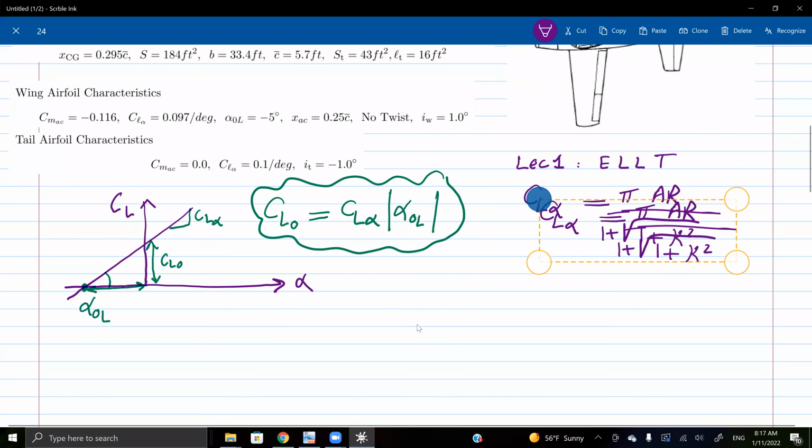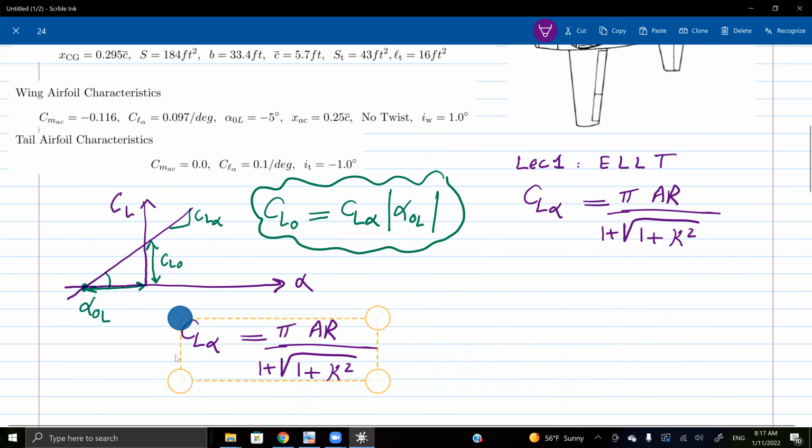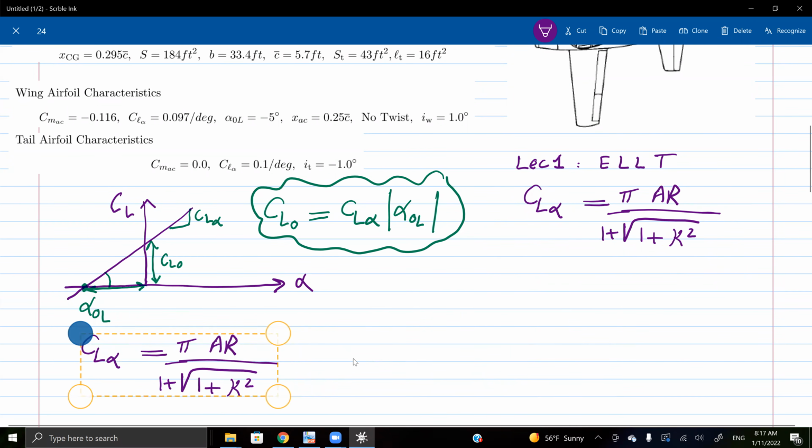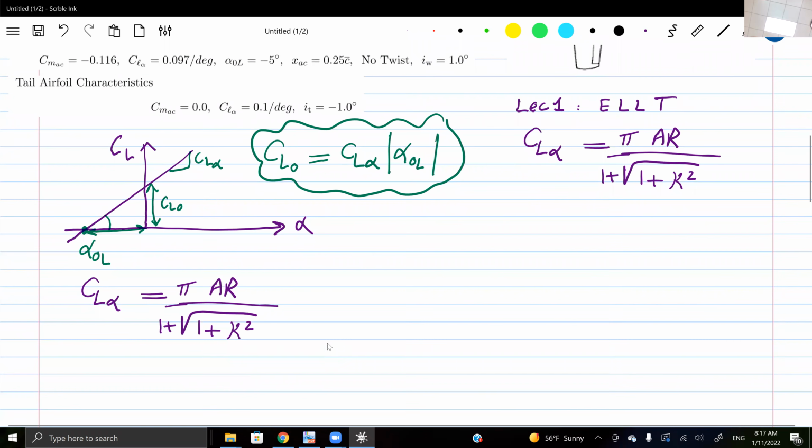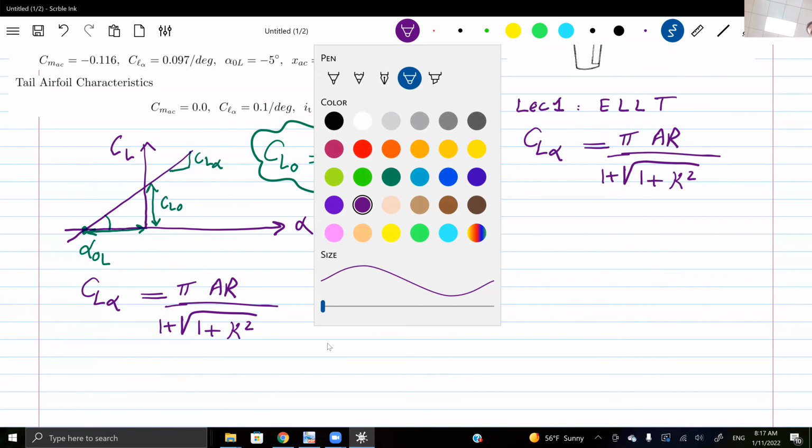Professor, could you just real quick go over again what CL alpha and C little l alpha is? Sure. C little l alpha, sometimes we give it the name A naught, is for the 2-dimensional airfoil. It's not just wing characteristics. So this is for 2-dimensional. The C large L alpha is 3-dimensional. And you can always get one from the other if you know the aspect ratio.